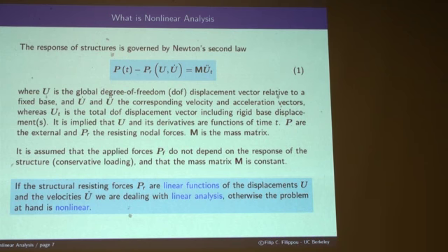So, for our simple purposes, we assume that the mass is constant and the applied forces are constant, in the sense that they only vary in time or in space, but they don't vary in terms of the displacements. And the only thing that is dependent on the displacements and the velocities is the resisting force vector PR. If these resisting forces are linear functions of the displacements and the velocities, we are dealing with linear analysis. Otherwise, the problem is nonlinear. Simple, right?